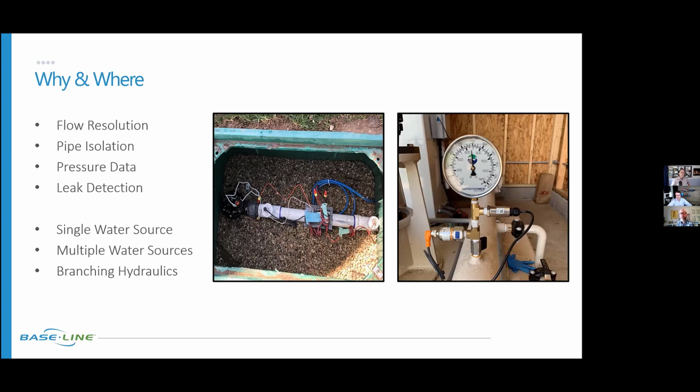Yeah, and on some of these sites, what happens is only one control can be the brain of the system. So what's happening is historically you had a pump station with some controls and an irrigation system with some controls, but they weren't really able to work together in harmony. And so what we're moving towards now is letting the baseline controller operate the system, and then the pump reacts to the demand that the controller is asking for. Mm-hmm. Nice. The VFD. Yep.